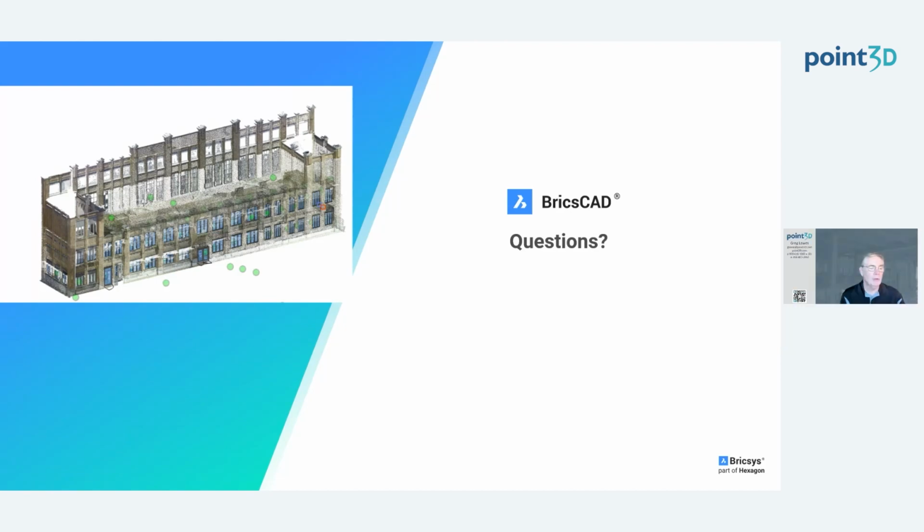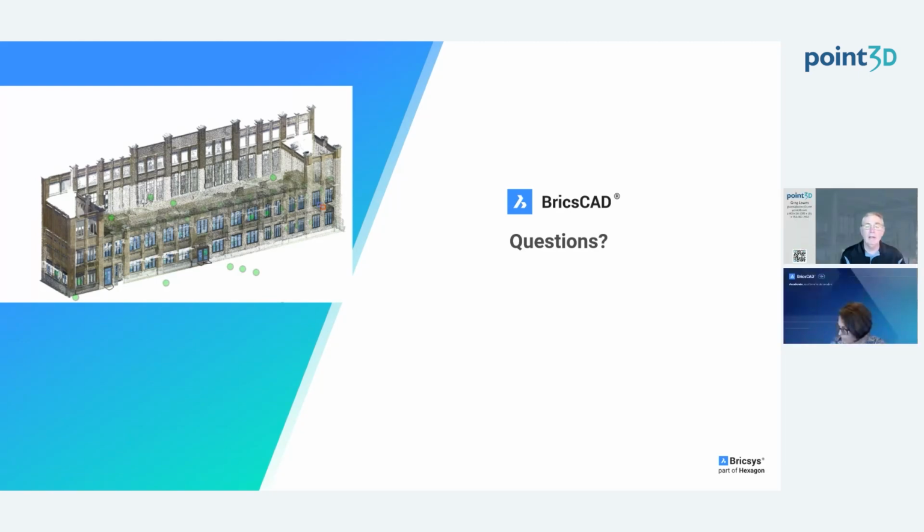And I have a question related, just from the support team here. The BricsCAD native point cloud format, different from the HSPC, that is still supported, correct? Yes. The way that you can process an HSPC, there's actually a system variable that you just turn that on, and then it will pre-process that as the HSPC. If you turn it off, it's just going to pre-process it as basically like an E57. So there's a switch for that.